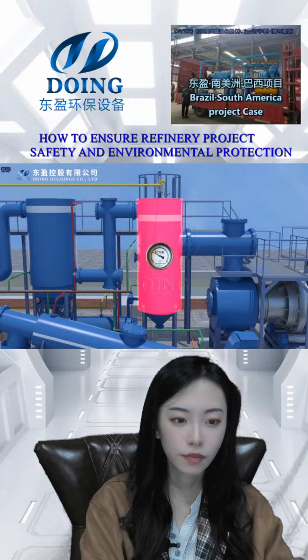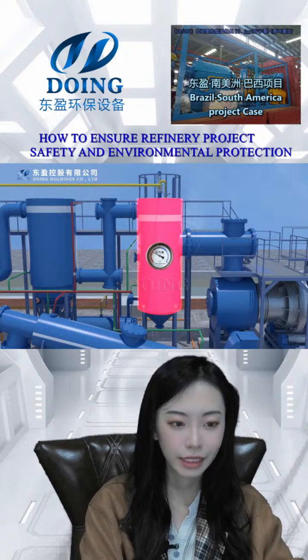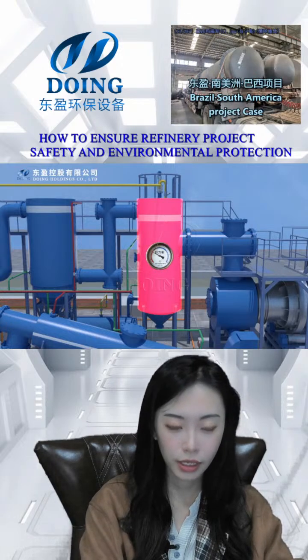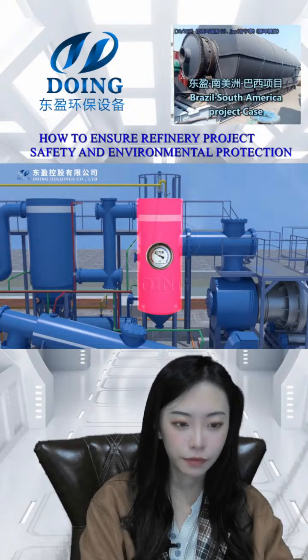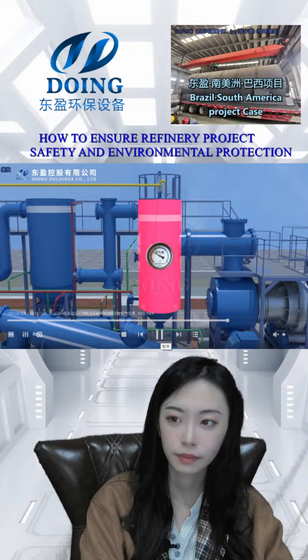And this is a safety device in the buffer tank, connected with the pressure relief valve. If the pressure is too high, more than 20 kilograms, the pressure relief valve will just automatically open to release the excess oil gas.